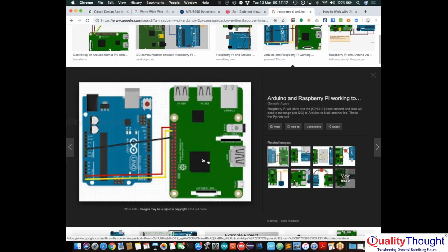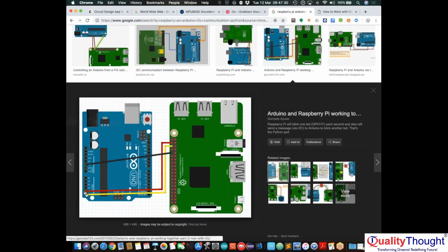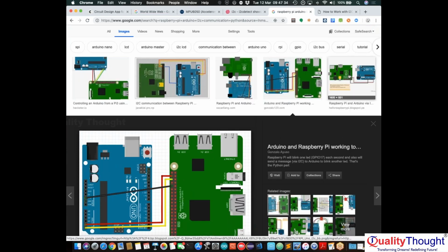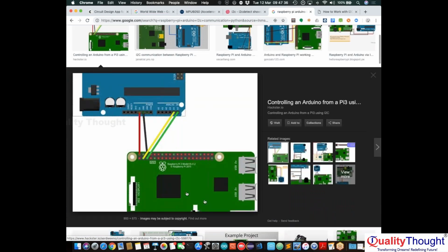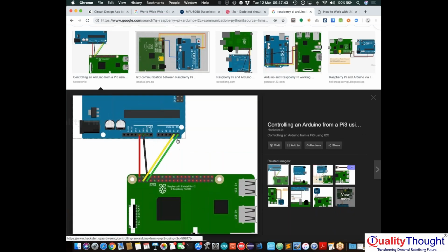Right, so you can see it here. The RX and TX are connected to the RX and TX of the Raspberry Pi. We can try using this particular thing, and SCL and SDA, which are connected here. You can try that, or you can try this way also. We have the alternative pins. Whatever actions you are trying to send will be sent as part of the I2C communications, and you would be doing that particular job.